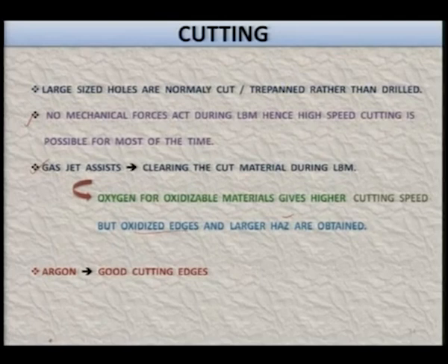Argon is a good assisting gas, with the help of which you do not get oxidized edges, and the cutting edges are also sharper and better compared to what you get in the case of oxygen.